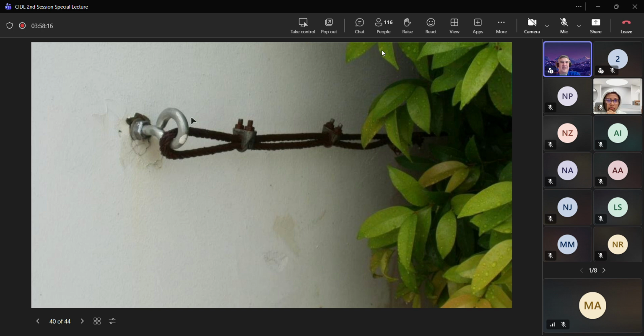Look closely at this picture. This is 6 months after they put this fall protection in. And you can see the eye bolts, the anchor points, are starting to show signs of deterioration already. So that's the difference between design and redesign. I wouldn't trust this. And again, I don't know how I'm going to get back there.